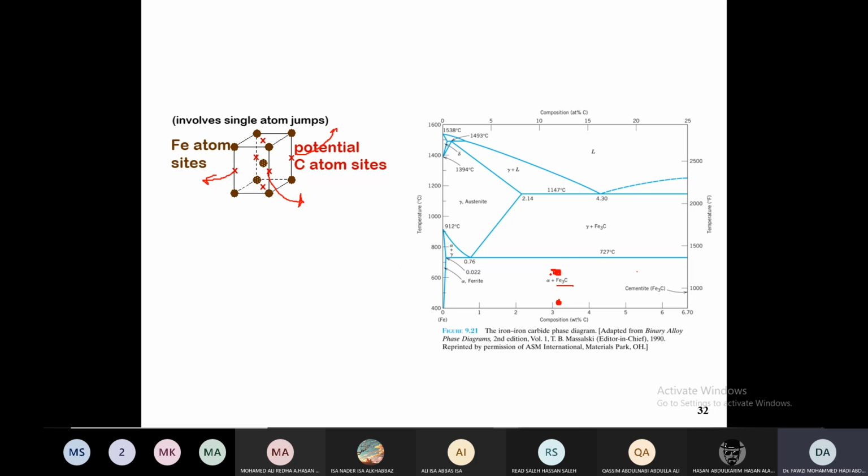When we take the temperature to 600 degrees centigrade and keep it for some time like that, what is going to happen? That microstructure basically will, for the same reason that we said how the spheroidite forms, remember? It's going to form the tempered martensite, but since we have the material for some time at high temperature, the material will behave coarser.